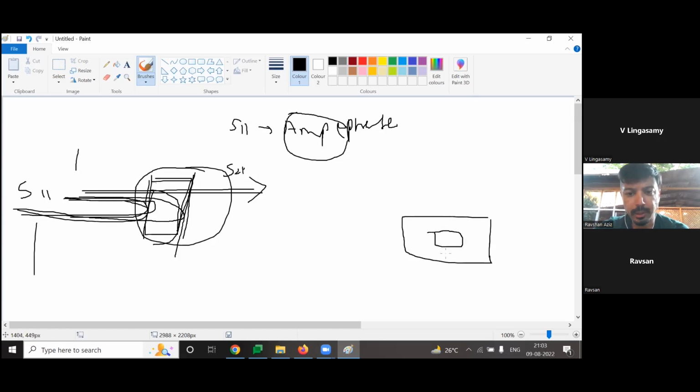The signal impinges, passes through the substrate, which is a dielectric, so it experiences some losses. Then it hits the reflector or ground plane and comes back, again experiencing losses. The reflector is also not a perfect electric conductor, so during reflection it causes some losses too.